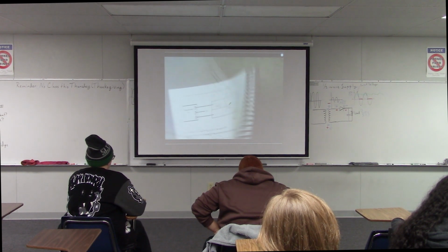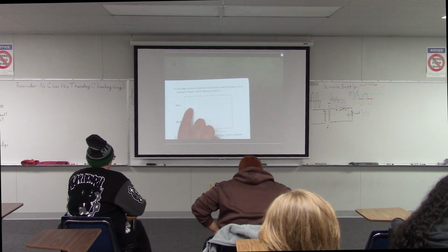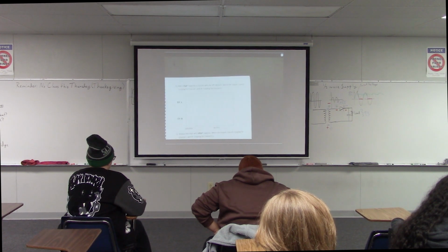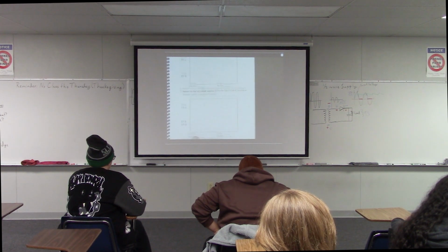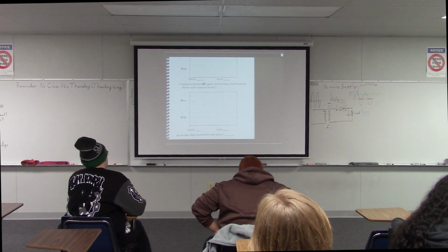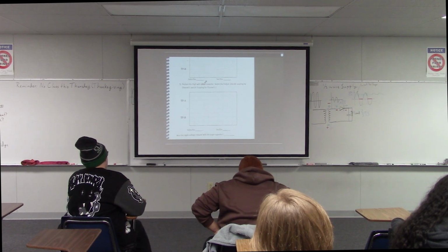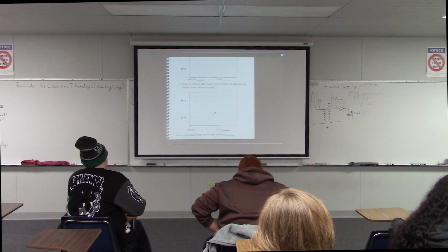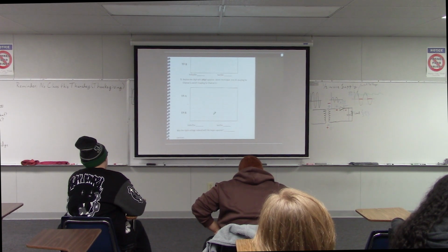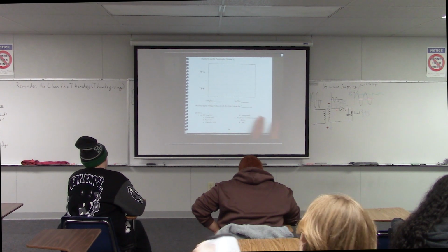Okay? So you're going to do that with the 10 microfarad capacitor. You're going to sketch your output here. And then you're going to repeat that with a 100 microfarad capacitor. The only thing you change in that circuit is you pull out the first capacitor, you plug in the second one, and then you sketch the new signal down there. And then there's just a couple questions at the end of that lab.